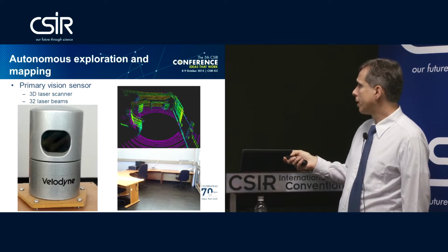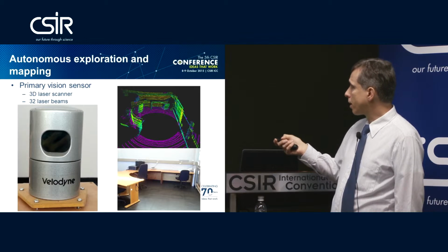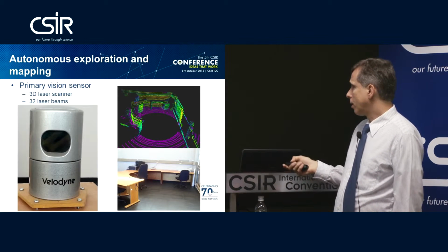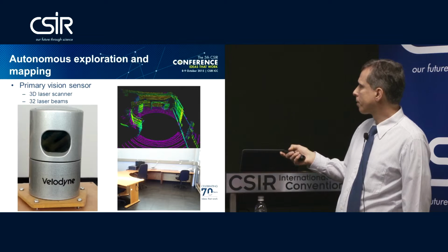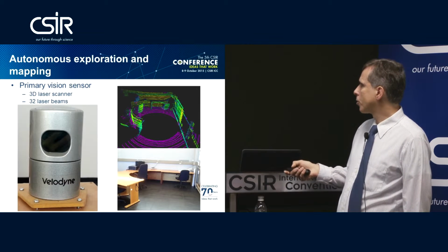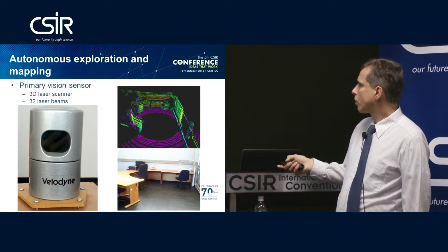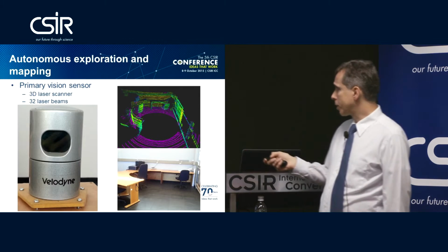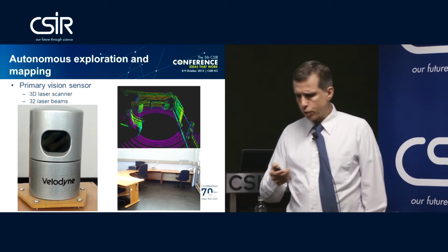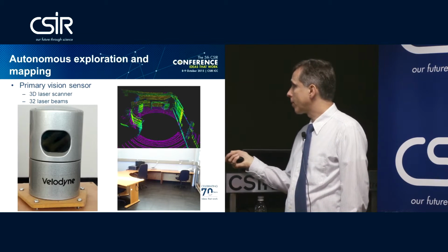This is called a point cloud. So every place in that environment where there was a return from a laser beam, we would get a point in this representation. If we look at this, we can see a couple of chairs in this environment. We can see the backs of these chairs in this point cloud. Also, the support structures for these tables are also there. You can see them on the left here and at the back. The two walls, the one at the back and the one at the right, are also represented there. And if you look closely, there's a computer screen, which is also represented in there. And not to mention the floor here as well. These purple points are reflections from the floor itself. So this is the kind of information that will go from this sensor down to the computer in our system.